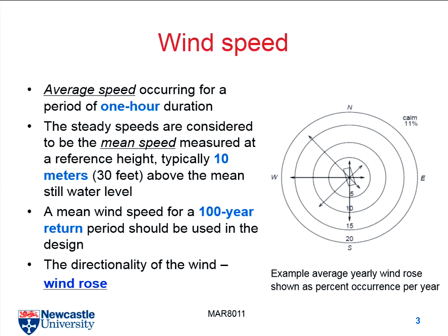But sometimes maybe you have a definition for 50 years or 200 years. Roughly, the meaning is like this. If you design something based on the value with the confidence of a 100-year return period, it's not likely to happen again in these 100 years, but it's not a promise. Please remember that. It's a criterion, but it's not a promise.